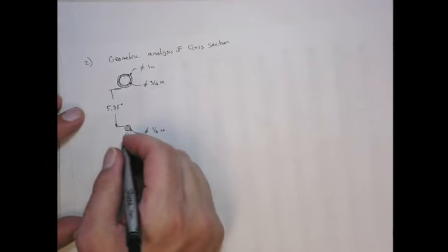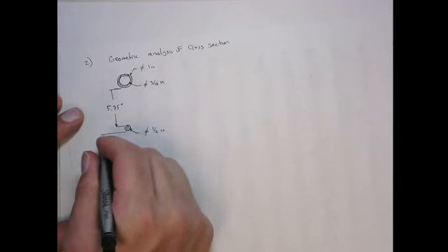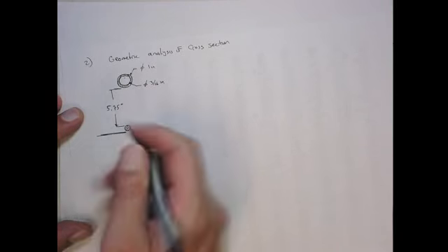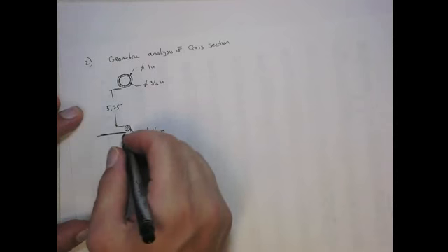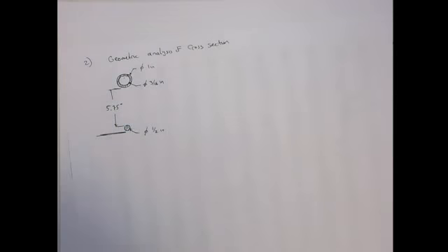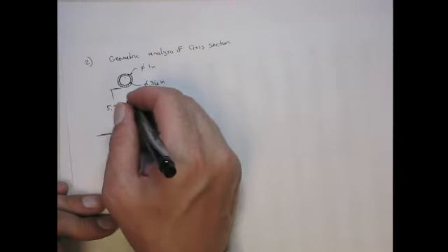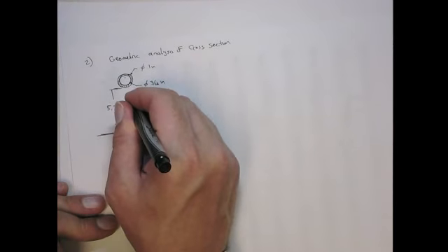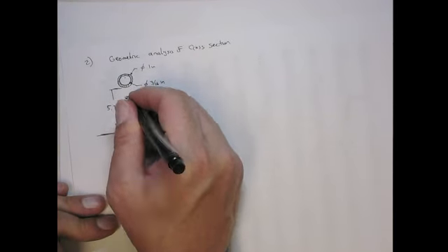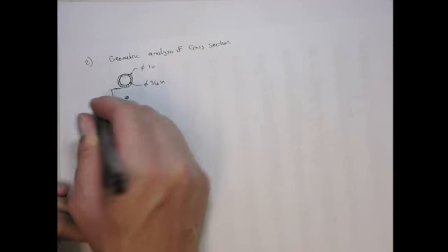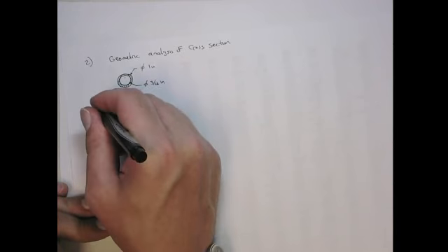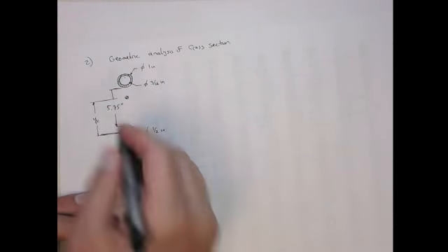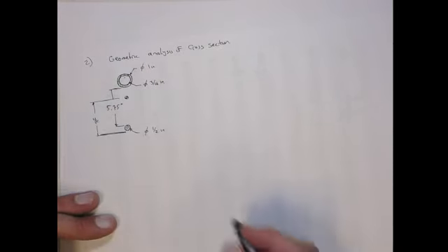All right, so let's pick our datum that we're going to use to get the location of the neutral axis, the bottom of this circle. To get the location of the neutral axis, right, we need to get the centroid. Here's that centroid location. We want to compute this distance, and we're going to call that YC. That's the location of the centroid of the composite body, right? I don't know where that is.